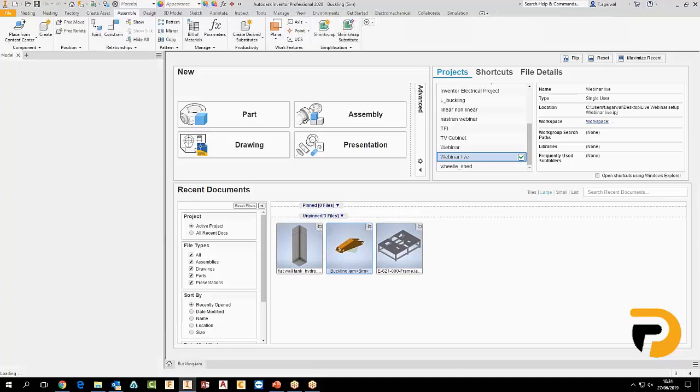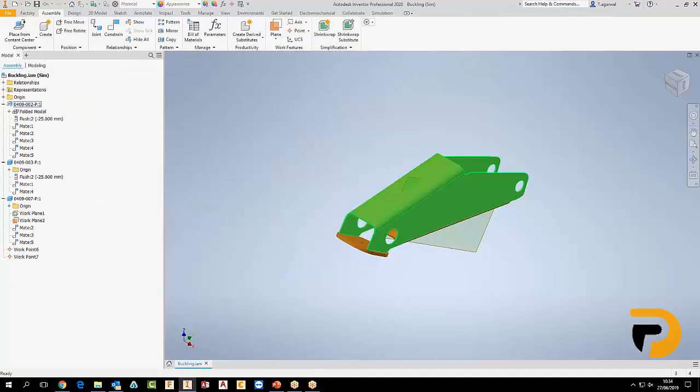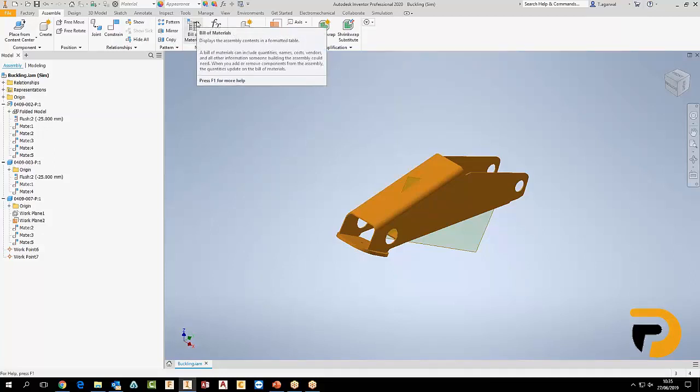Okay, so what is buckling? Buckling is a failure mode quite commonly experienced for mechanical components and structures. Linear buckling is also called eigenvalue buckling or Euler buckling analysis. I'll tell you why it is when I analyze the results. I'll tell you why this name. And it predicts the theoretical buckling strength.